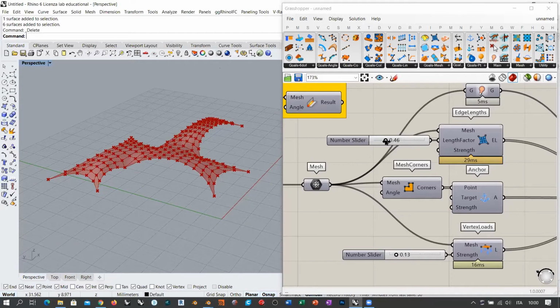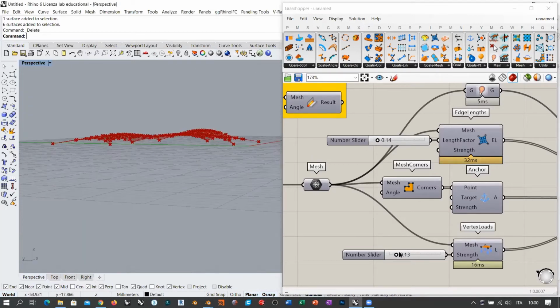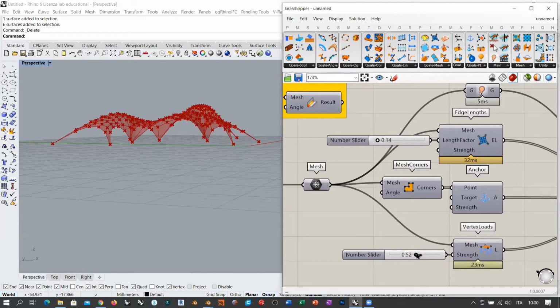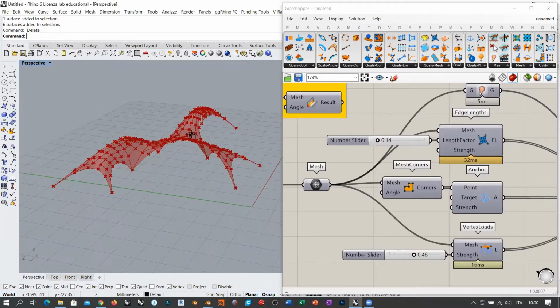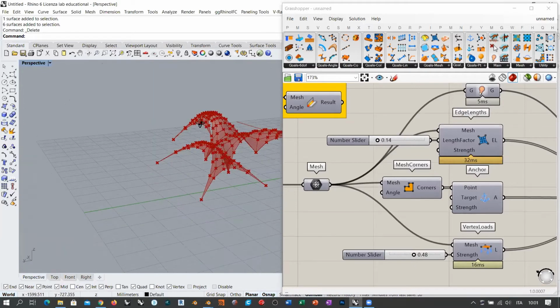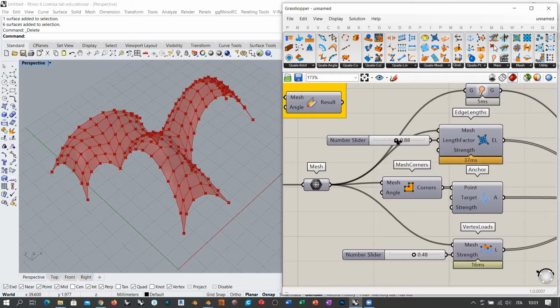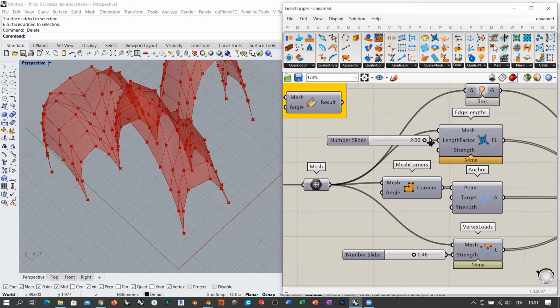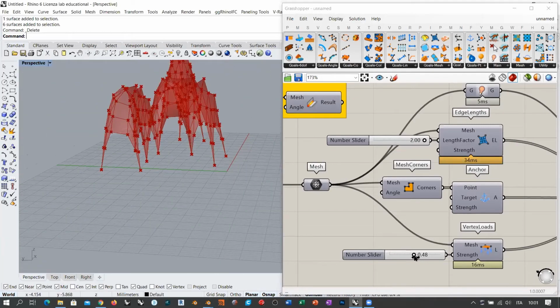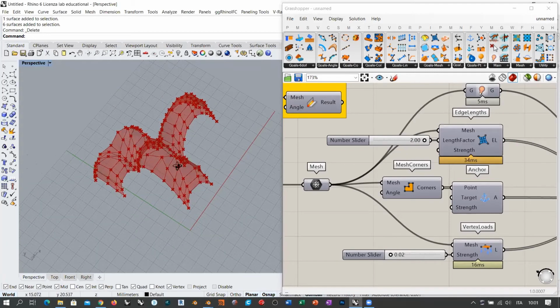And so if I create this kind of pretension, even if I apply a large value for this load, the deformation will be smaller because this object is more resistant because of this pretension, okay? If I, on the other hand, increase this, you see that the deformation becomes larger even with a smaller value of the load that I am applying, okay?